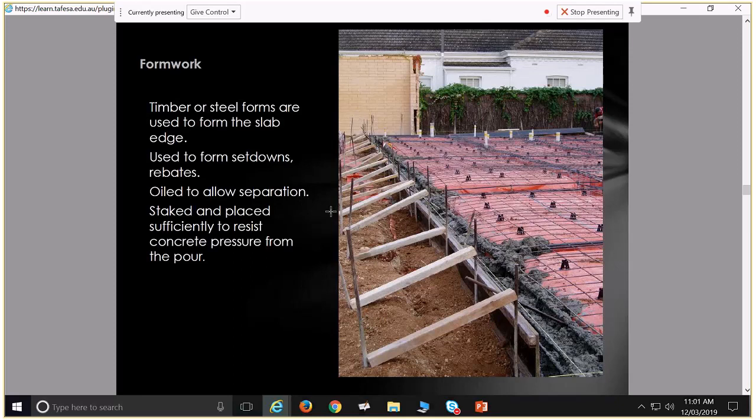This room doesn't have any exposed concrete in it. If we look out the window there, we see that lift shaft. That's not really high quality concrete forming, in that they've recycled their sheets of formwork. Your formwork gets banged around, it gets nail holes in it and all that sort of stuff over time. If you're reusing your sheets, you end up getting marks and funny edges happening on it. But I think there are some sections of concrete in this building that are finished really nicely. It's a bit more high end. That's where you're using brand new sheets of form ply. You silicone all the joins to get them really flush. You get really smooth surfaces.